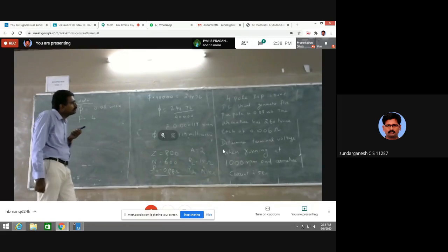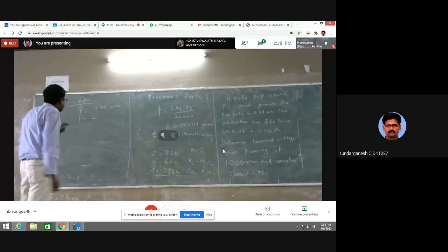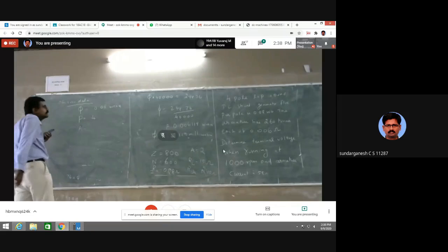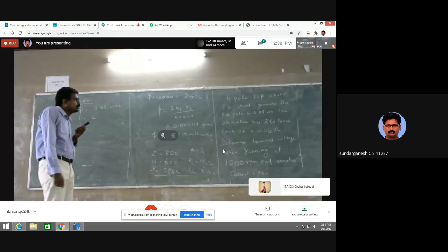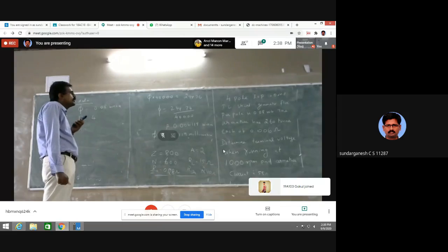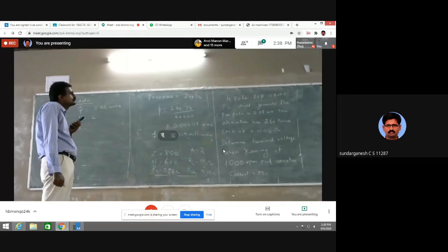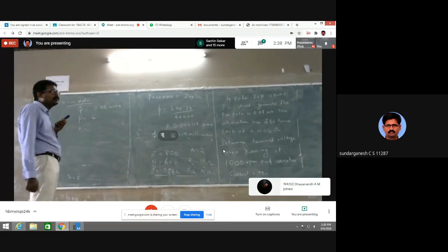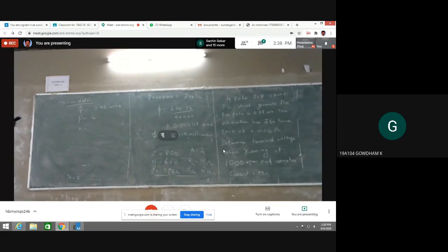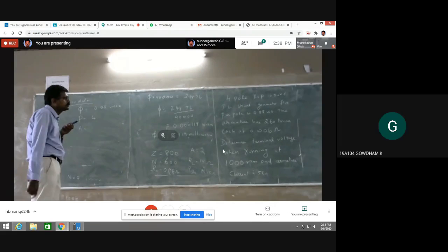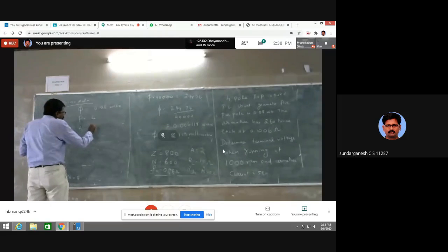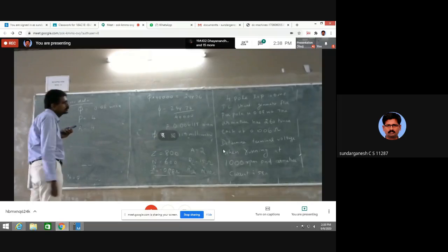Okay, what is the number of parallel paths, A? In this problem, what is A? They are given lap wound. So if it is lap winding, what is A? A equal to P or A equal to 2? Tell me whether it is A equal to P. So A is equal to 4.